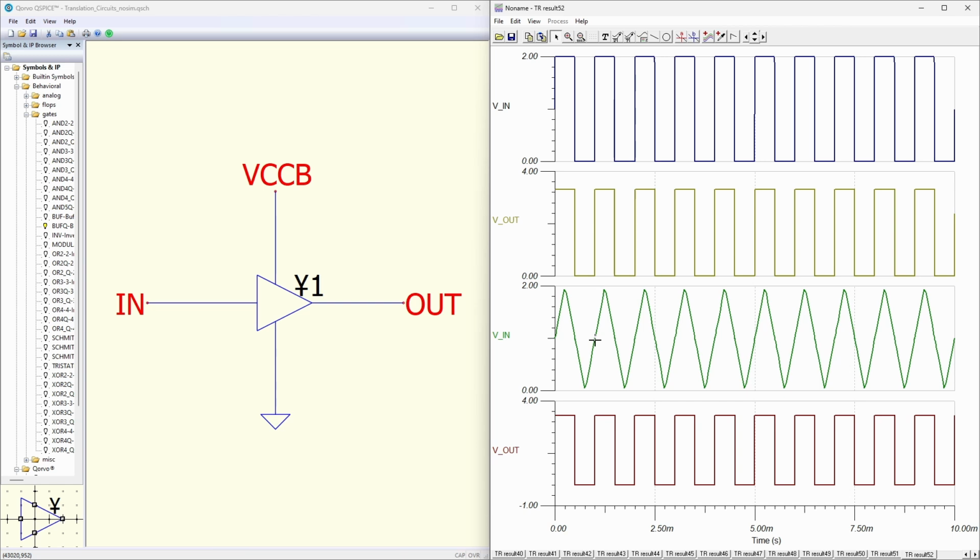There is one downside to this, and that is increased power consumption. If you go pull up a datasheet for one of these devices, you'll find that TTL compatible devices pull a decent amount of current whenever you're not putting in a voltage that's all the way at the rail. So generally speaking, with CMOS devices, you want your input voltage to be the same as your supply voltage, and that reduces the amount of current shooting through the inputs.